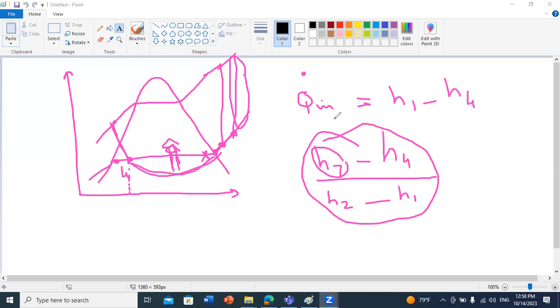For example, here we studied together this cycle. I can tell you to try to improve the efficiency by just looking at your formula. You can check, for example, if I increase H1, this will maybe make the work of the compressor more difficult because I will have a larger difference H2 minus H1. So this might affect my case in a negative way, so I should optimize the location here.